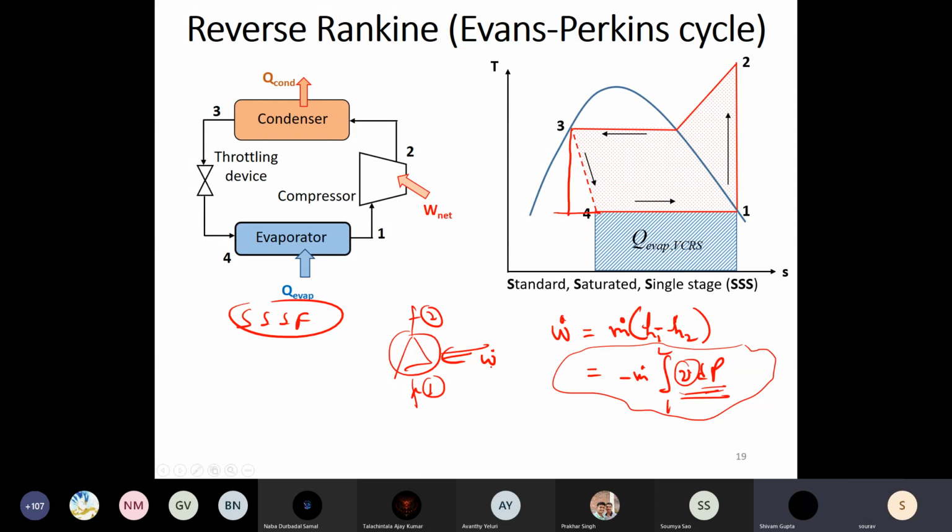Okay, so you have a look at this from the thermodynamics text. An important inference from this is the expression for work transfer. For the time being, forget about the mass flow rate; let's say it is 1. If you are compressing a fluid which has a very large specific volume, then the work done by you would be very, very high. Hence, to compress a gas with very low density, and therefore very large specific volume, you have to do a lot of work.